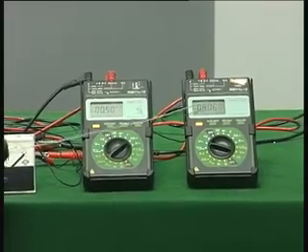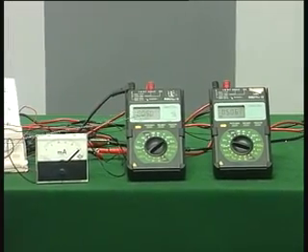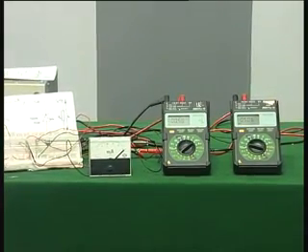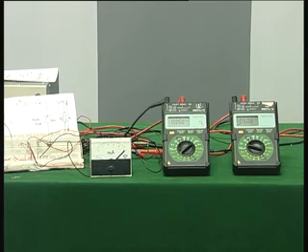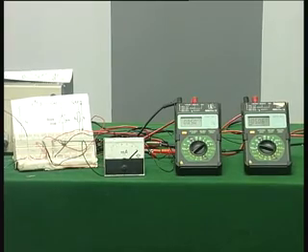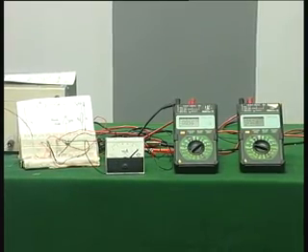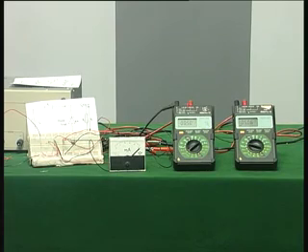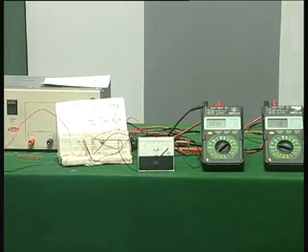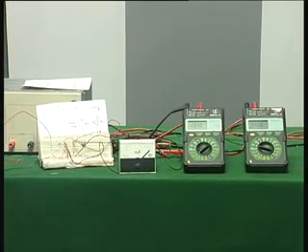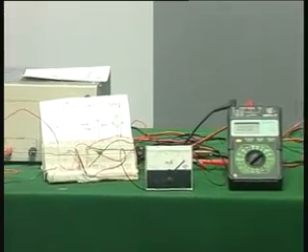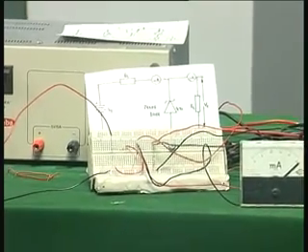So you find this voltage is still remaining constant, but the load current has decreased, and the series current is as high as ever. All the time it was high. So you can see a Zener diode can be used to regulate an unregulated power supply, and we can now calculate, by changing the input by a known value, what the change in the output voltage is. That will tell us about line regulation, and similarly I can vary the current by changing the resistance and find out by how much the voltage is changing.